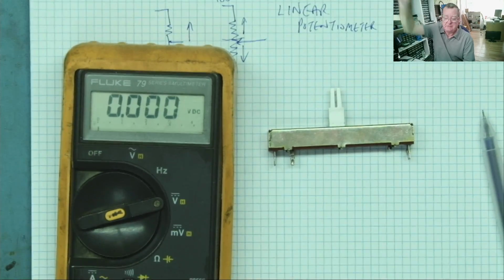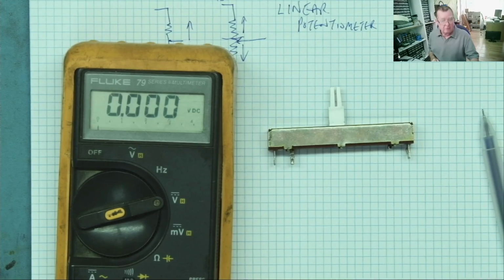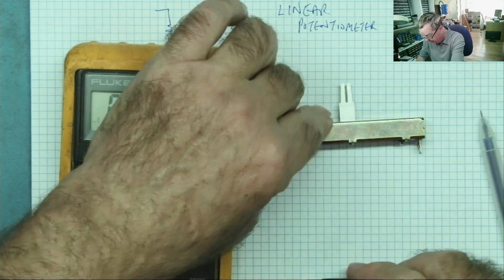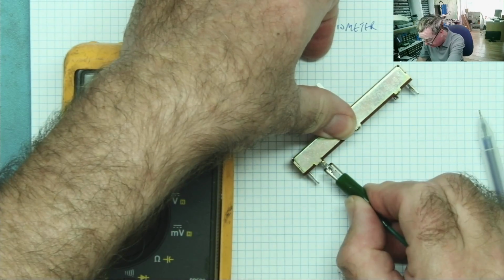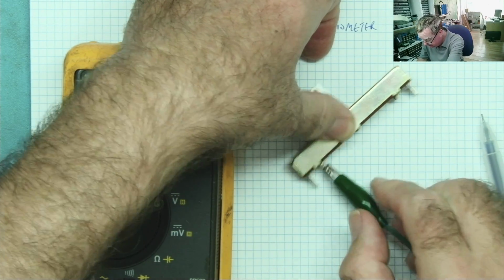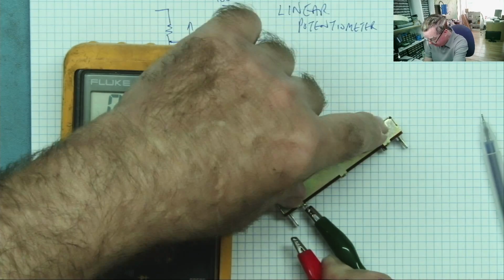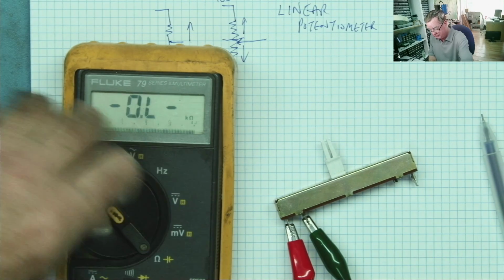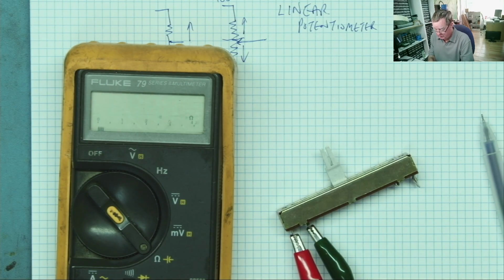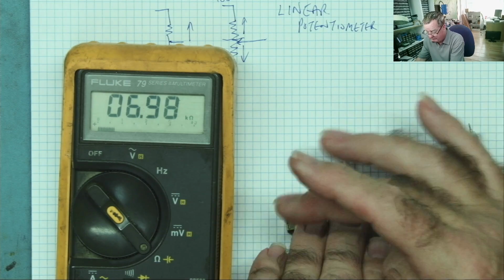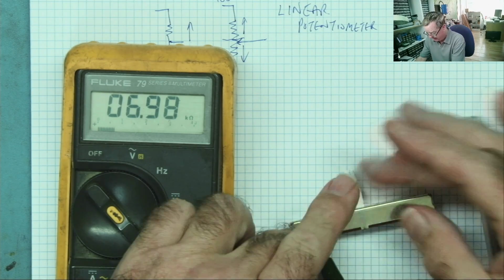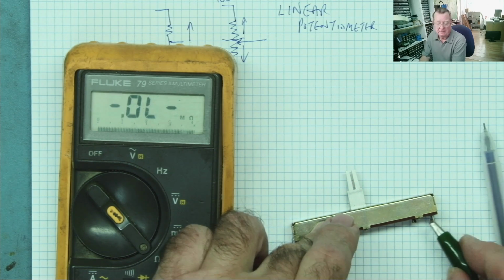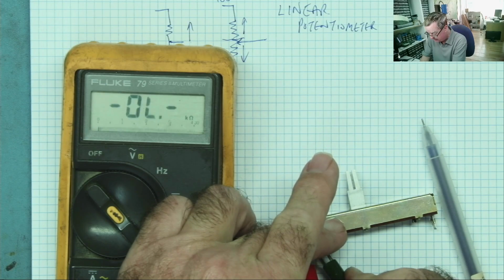So what that means is we can get some crocodile clip leads again, because we'll need them. So we'll connect to the wiper. Okay, we're on the wiper there. I'll connect my multimeter now to the end of the track, one end of the track. We'll go to resistance range. And you can see that the value in the middle is about 7K. If I go all the way across the track, it's 46, 47. It's close to what we'd expect for 50, okay?